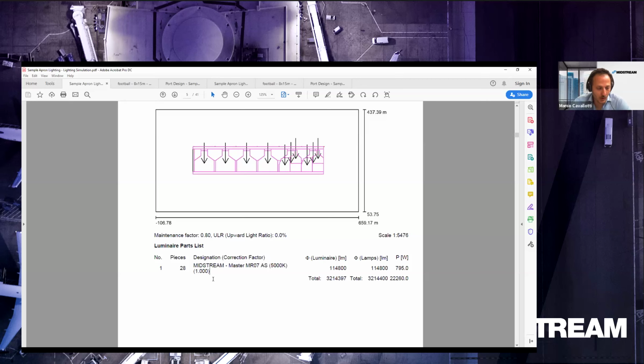So in case, for example, one luminaire is equipped with, I don't know, a symmetric optic, we have the photometric file tested in the lab without and with the visor. There's a difference, obviously, because the visor adds a light loss of, for example, about 7%. So we prefer to have a photometric file which is already exactly as the final product which will be installed, instead of adding a correction factor. So that's the reason why our one is 1. Usually it can be, I don't know, 0.95 or 0.80 according to the light loss that you have.